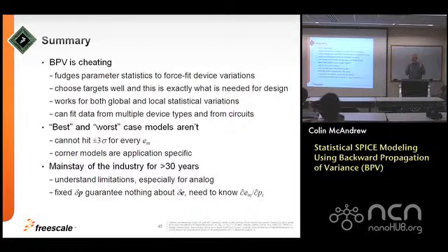The reason for doing that is that if you push a parameter to a corner, to a ±3 sigma value, that's where simulation issues with the model parameters will show up. An extreme example is sometimes we find that some resistances that aren't observable will have a huge variation, and so it means really we shouldn't be including them in the analysis. Let me give you something that's more appropriate. The non-ideal component of current in a bipolar transistor has a very large variation statistically. So if I want to take a -3 sigma value from that, I actually get a negative number. And so the plus or minus 3 sigmas is to exercise each parameter over its full range to make sure that there aren't any other simulation issues that come from that.